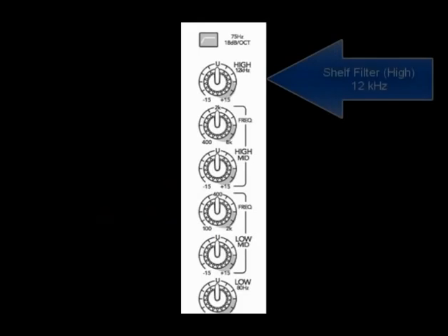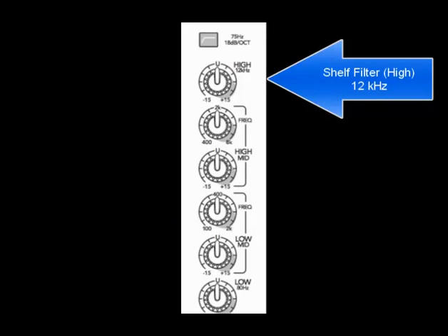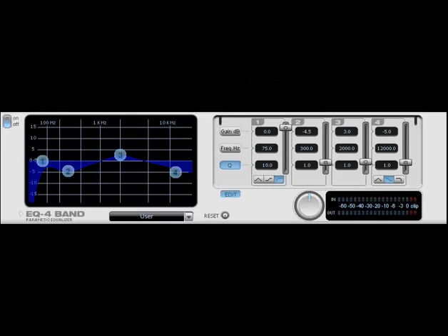Finally, there is the high shelf filter. This is configured at 12 kHz with a variable amplitude. We'll set the gain at negative 5 decibels and the Q at 1. Here we get a decreased gain, then a leveling of the gain, like a shelf. This is useful for cutting down on some of the higher frequency noise.